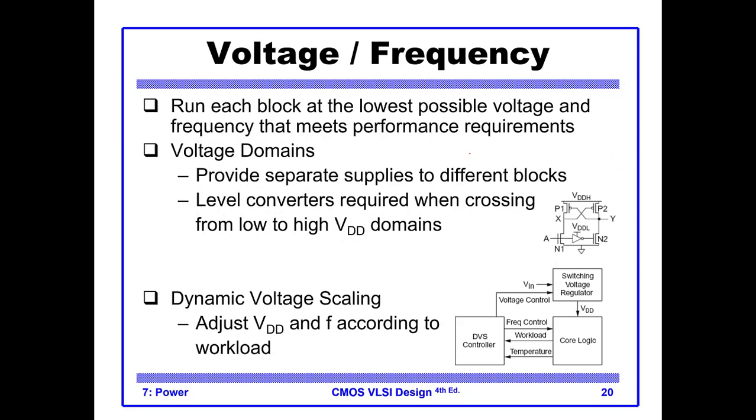Then again, the dynamic power is alpha c v square f. So we can control these two, voltage and frequency, and if you control both simultaneously, it is called dynamic voltage frequency scaling, or DVFS.